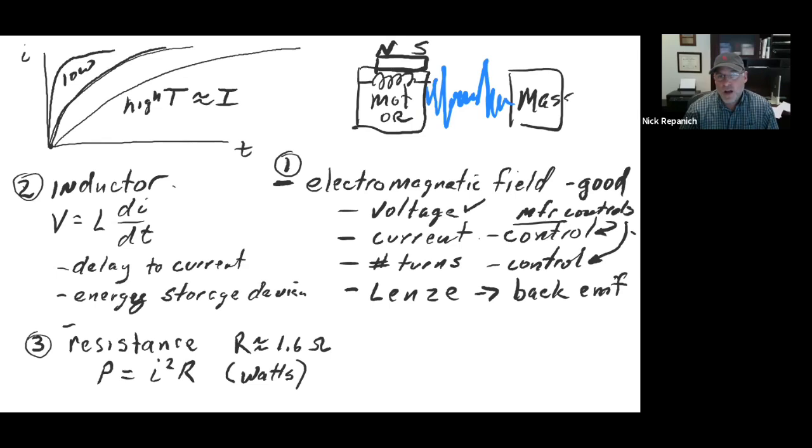So that's the problem with the motor: the whole idea is to run current through it, but current squared starts adding up to watts. And so what limits, this is kind of an important thing to take away from this, no matter what motor they make and who makes it and how they wind it, the thing that ultimately limits the torque and speed, and torque times speed is power.